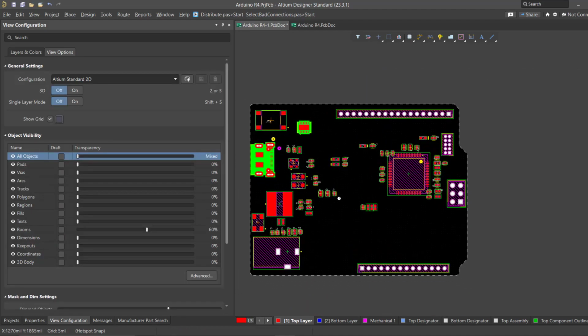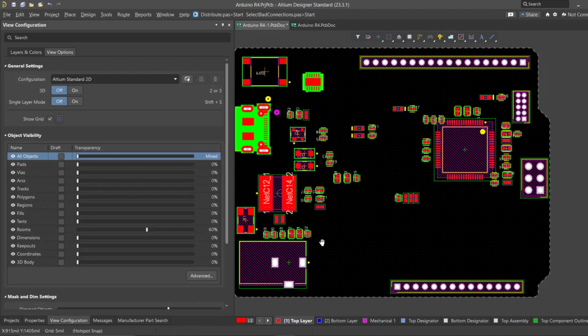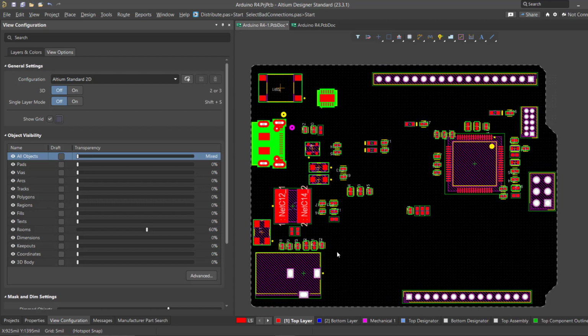After you've successfully dragged and placed all the components on the PCB layout, it's a great practice to validate the physical placement. You can achieve this by activating the 3D view in Altium Designer. The 3D view provides a realistic representation of how your components will physically sit on the board.